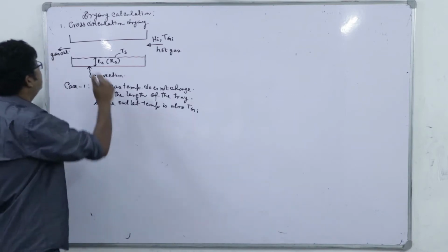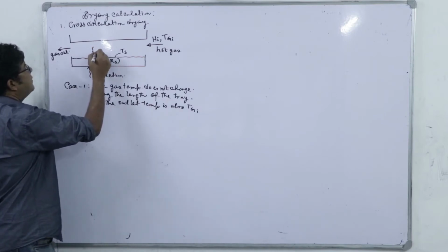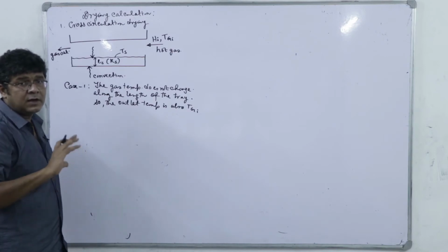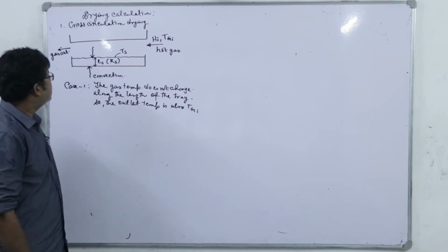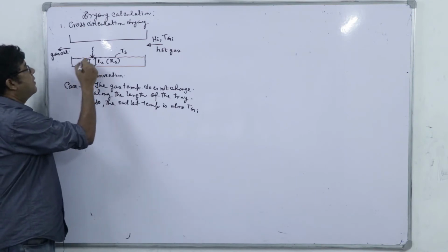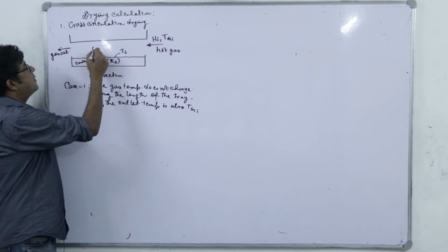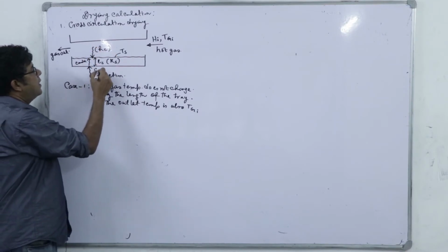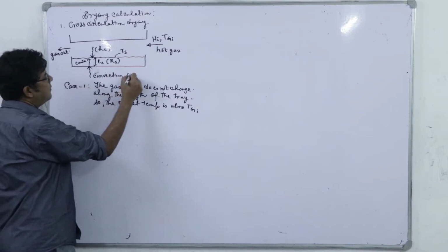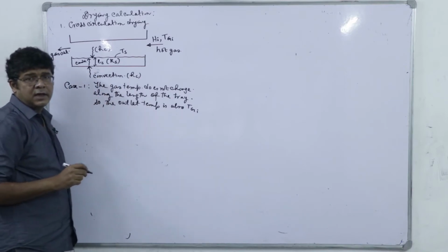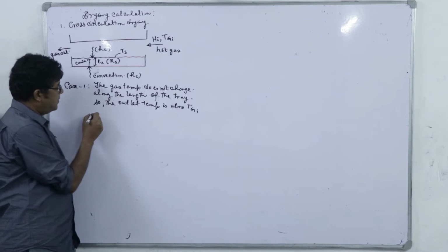So, first you see we have convective transfer here from the top, but from the bottom as well we have a combined convection plus conduction through it, right. So, here we have conduction. So, this heat transfer coefficient is Hc, and for the convection it is Hc, but for conduction the resistance we can write as Ls by Ks, right.